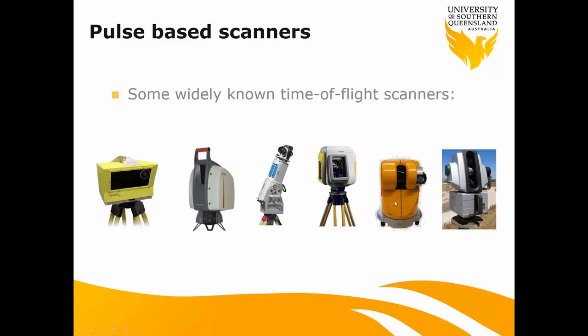The other laser scanners have an internal high-resolution digital camera, but with the Riegl you have to use an external digital camera. Before or after scanning, you can take photos of the scanned object to help with point classification or segmentation, or even 3D modeling.